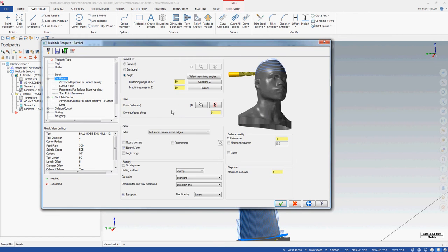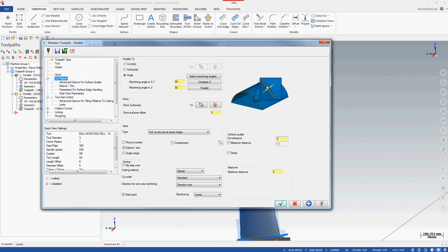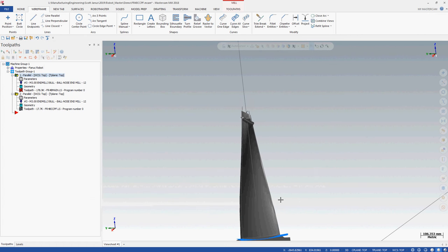Now because this is tapered, it gets a little bit off. I talked to Pablo about this, how I will create a separate surface so that the curve here and the curve here are the same width, so that I don't have this tapering effect. But anyway, you can set your start points. You have tool axis control. So I'm using a 5-axis, and if I want to change my lead or tilt angle, I can do that. I can show you that here. Let's just do a quick